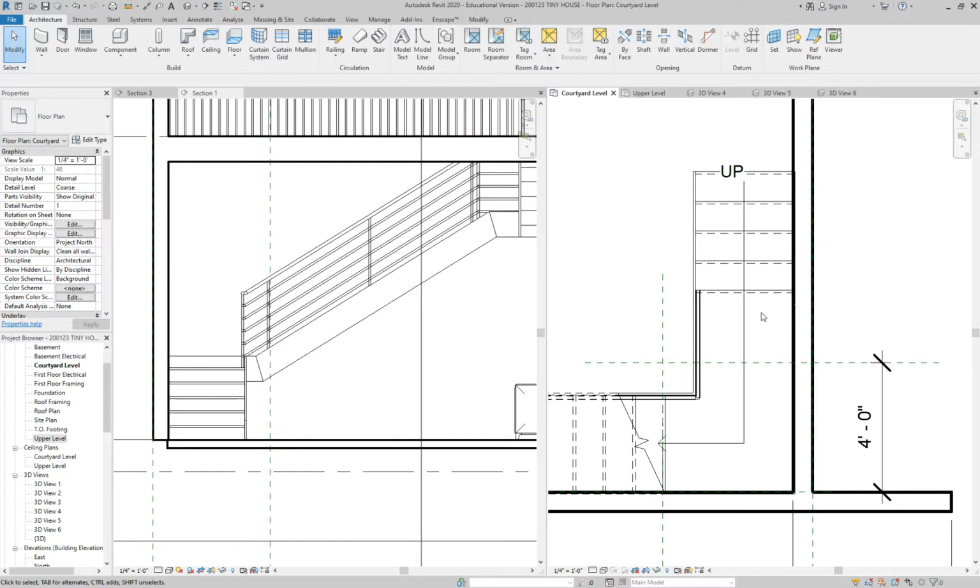And then railings. So I would say that railings and stairs are really similar to a lot of the things that we've done in the past where we've had to sketch something. The one exception is that stairs and railings, they don't have to be a closed loop, right? When we did floors, when we did roofs, those have to be a closed loop. Revit needs to know where those start and where those stop. You see the difference between the two? So we're sketching, one of them sketching a line, one of them is sketching a loop.